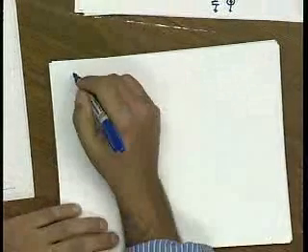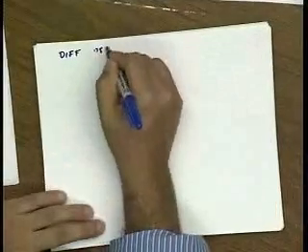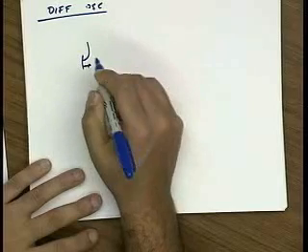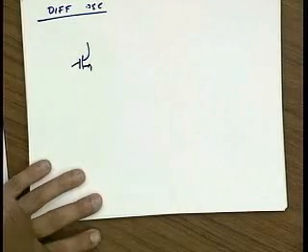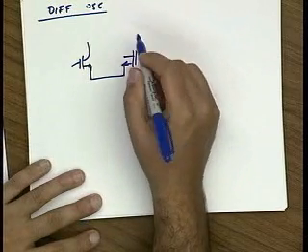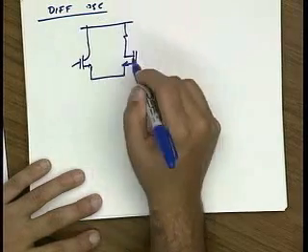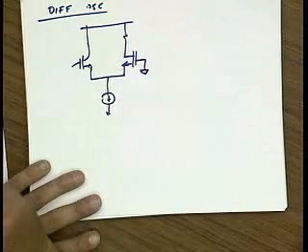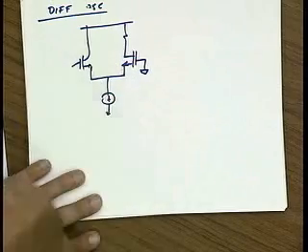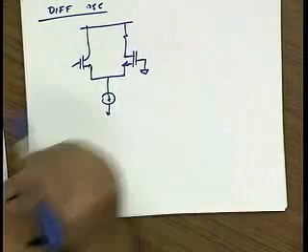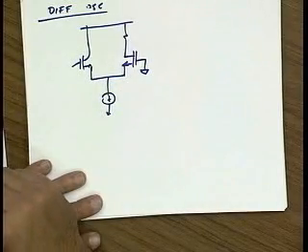All right. Well, let's talk now about differential oscillators. So let me build this up a little bit differently. Let me just take a two-stage amplifier, and let me take a broadband two-stage amplifier. So one nice broadband two-stage amplifier is a diff pair if I run it single-ended. In other words, I'm going to ground this side. I'm going to have a follower driving a common gate amplifier. And very early in this class, we learned that this is a very nice broadband amplifier.